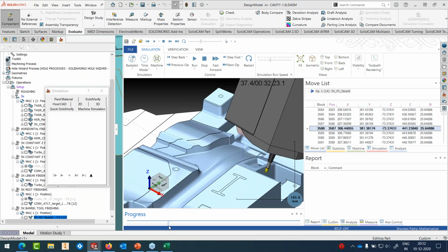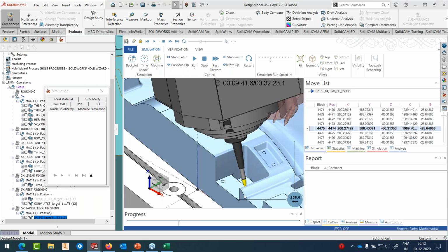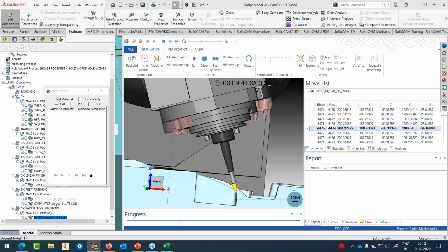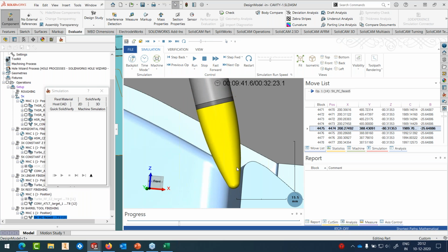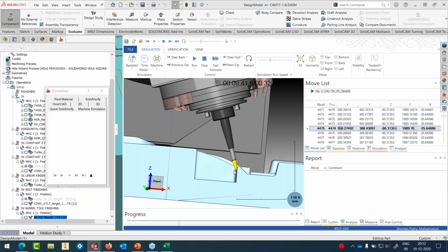The contact here is basically on the large radius. We are using the large radius, the R80, to generate the contact. Very important: we are not using the front tip, which is just R2. I will not get the scallop using the front tip, but only when I use this large radius. So I have tilted the tool in such a way that I'm using the large radius.